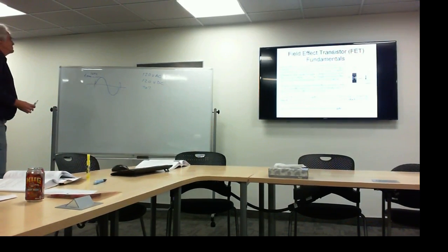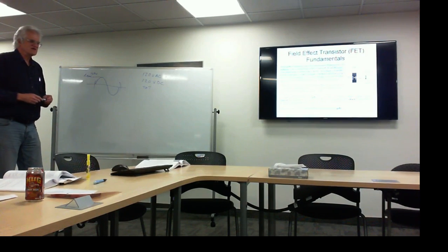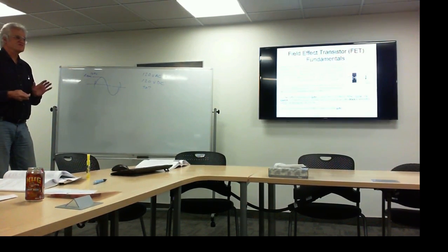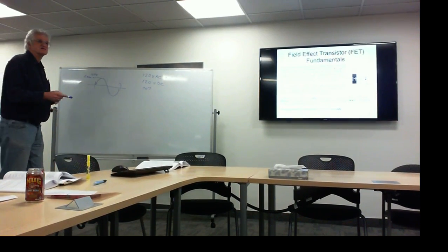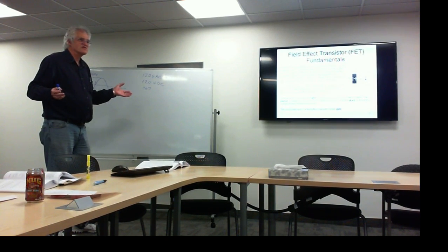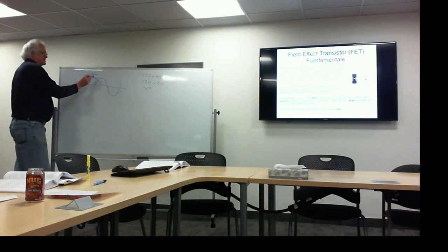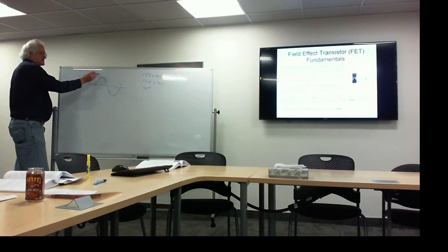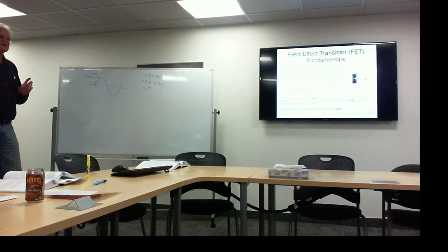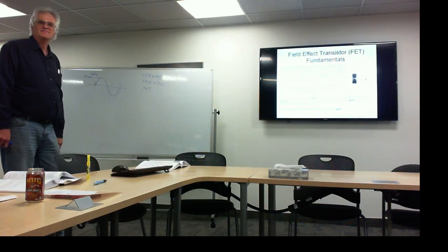The reason I'm saying it, remember we were talking a few minutes ago, I said one of the specifications of a diode was peak inverse or peak reverse voltage. So now if you're using that in a 120 volt circuit where we're going to rectify, you have to remember that the diode doesn't only see the 120 volts, it actually sees the peak value. It actually sees 169 volt peak value. So you have to take that into consideration if you're actually making a circuit. Does that make sense?